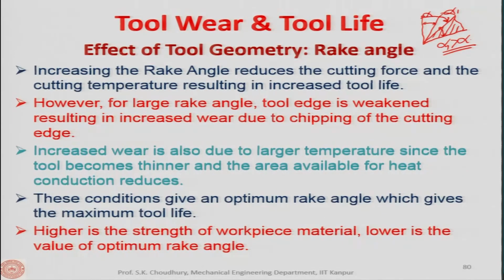So, these are the two reasons. One is the tool is getting weakened, so it can actually break, and the tool wear can be more. Okay. Second reason is that the tool wear will be more because of the thermal softening of the tool, because it is getting thinner and less material is available for the heat conduction from this tool.